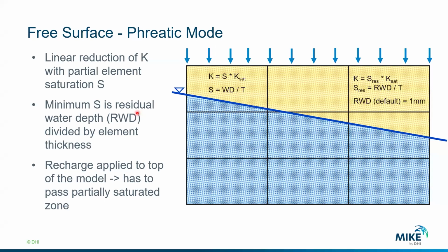So one option, when you solve the groundwater models in 2D or in 3D, is called phreatic. You say, my system is unconfined, and in unconfined I have multiple methods. One of these methods is called phreatic mode. Phreatic mode is a simplified method. In the white paper or the FEFLOW book documentation, this is called pseudo-saturation, because it uses a simplified way to estimate the saturation in the elements. This simplified way depends on the water column or the water depth and the thickness of the element.